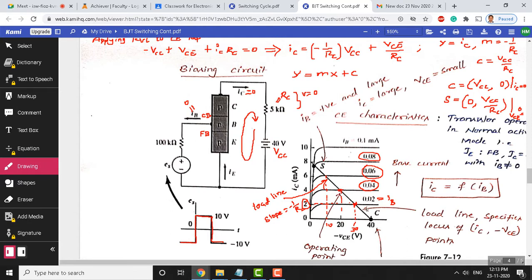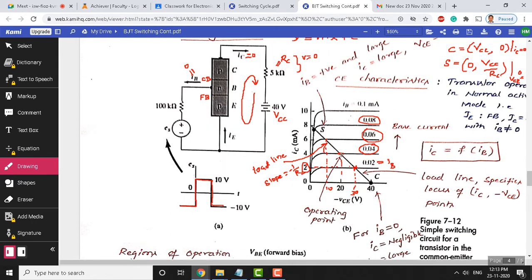Now, in electronic systems like a microprocessor, we need to operate between these two states, because usually in a microprocessor the transistor functions like a switch. Okay. So, it needs to operate in the off state, which means we need to move into the cutoff region. On state means it is the saturation region. That means we come across a situation wherein we need to move from cutoff to saturation, saturation to cutoff, many times, millions and billions of times within a given span of time.